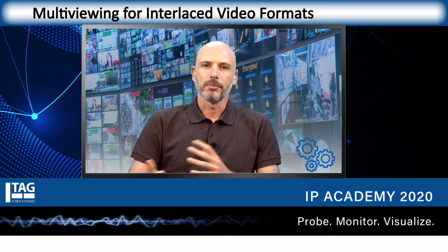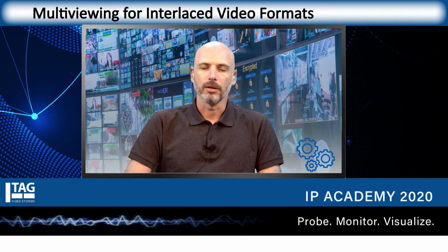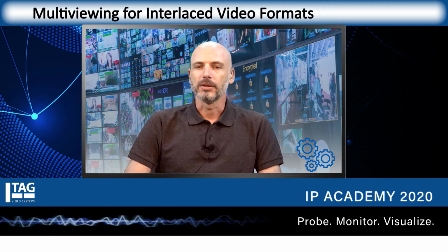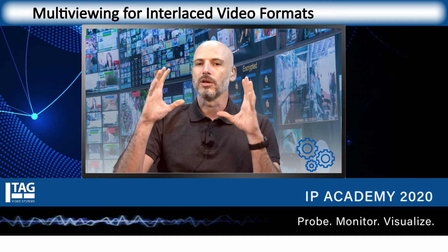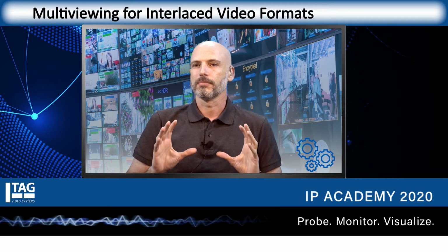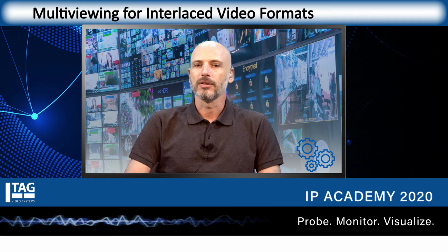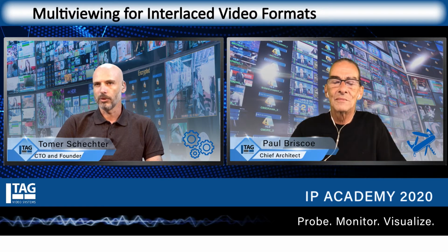But then when it was adapted back to the broadcast industry, the mainstream of the broadcast industry, you suddenly had to support 1080i, but HEVC doesn't support interlaced content natively. So HEVC can only handle interlaced content as 2 separate fields. It encodes each field as a separate frame, so it doesn't have any native understanding that the content is interlaced. It means that you lose on the bandwidth, on the compression, and it also means that you need to decode 2 separate frames in order to create your original interlaced frame.